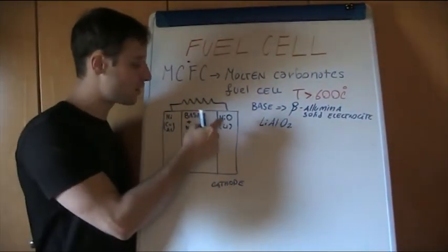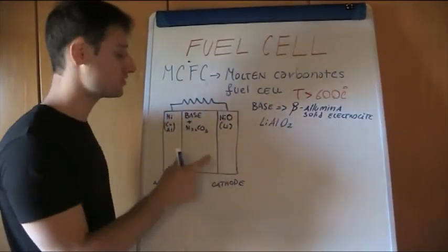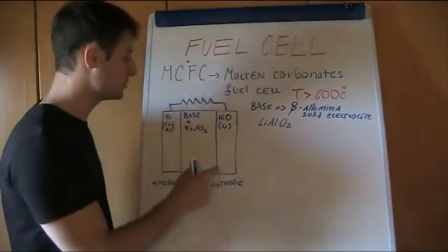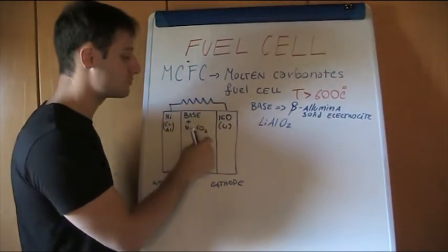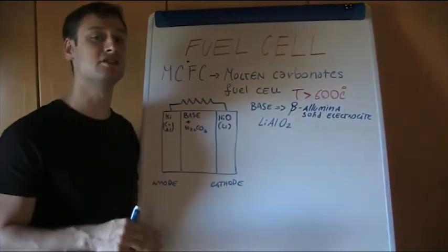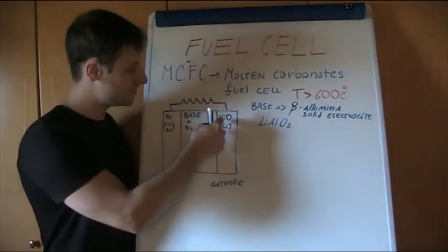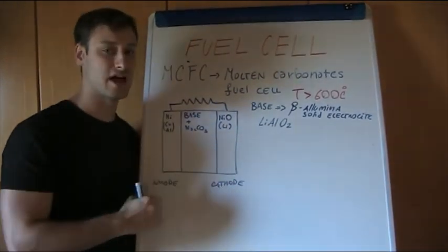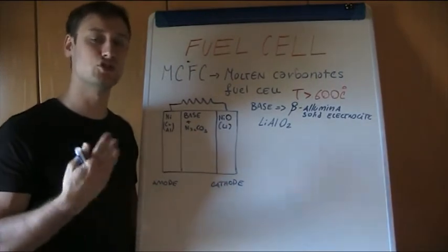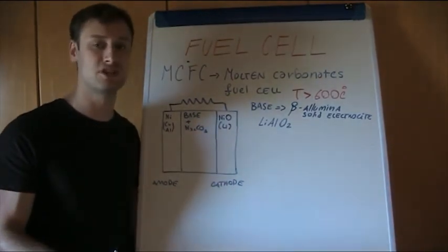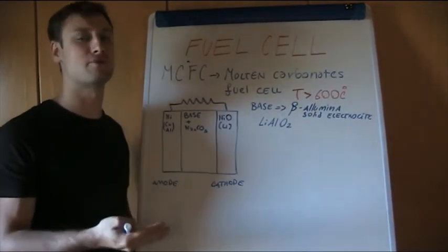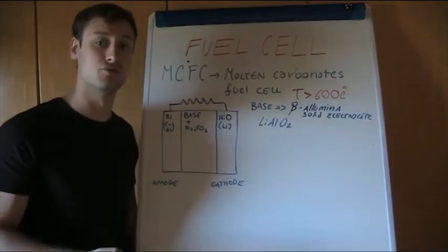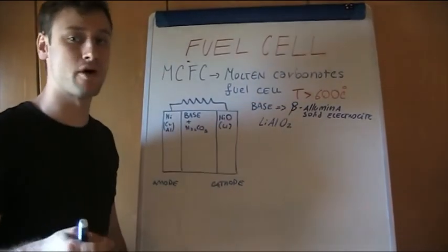And in this type of electrode, the cathode, it is important to say that the contact between the electrolyte, the carbonates, and it can promote the dissolution of this nickel oxide, releasing nickel inside the electrolyte. But we know that the nickel can increase the electrical conductivity, and we can even reach problems concerning short-circuiting conditions. So it's important to be aware of this.